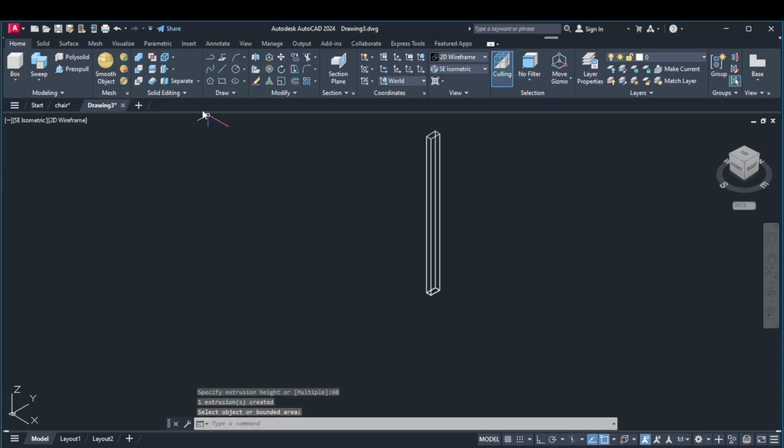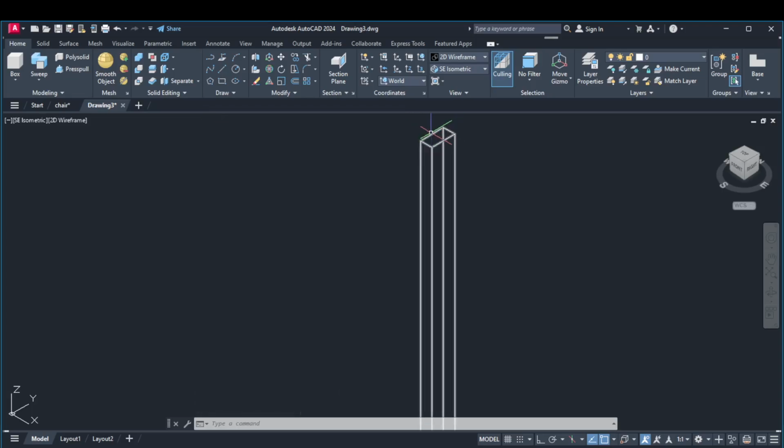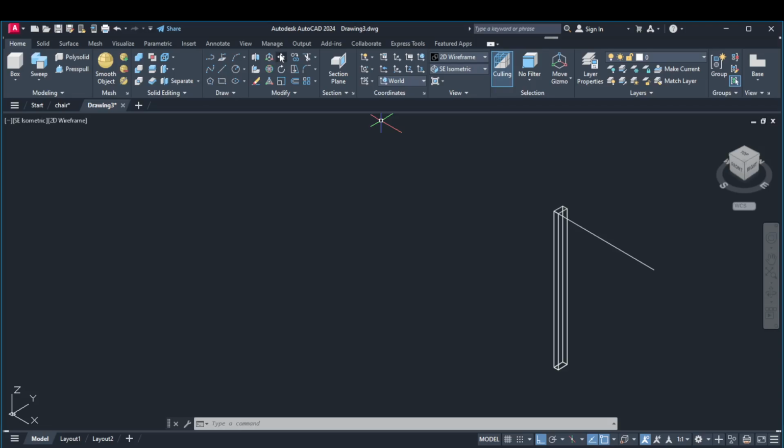Then we can also copy this. We'll copy from this end region, or we can just draw a line of 45 centimeters so that it cannot confuse us. For that line, we ensure that ortho is on, so that our line can only move in horizontal or vertical directions. Then we put 45, enter. So our end section on this other side should be 45. So we are copying this one, enter.